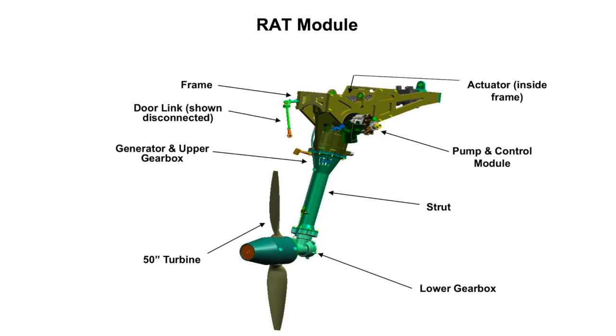The gearbox increases the turbine speed by a ratio of 2.13 to 1 to drive the generator. We can estimate the time it takes to reach the minimum turbine speed to permit hydraulic operation and the time it takes to reach the minimum turbine speed to permit electrical operation.